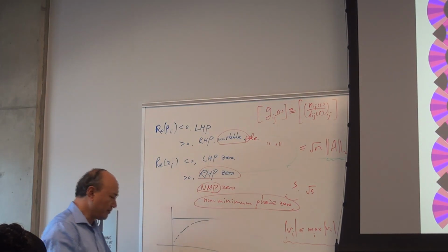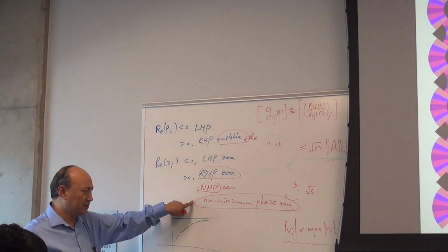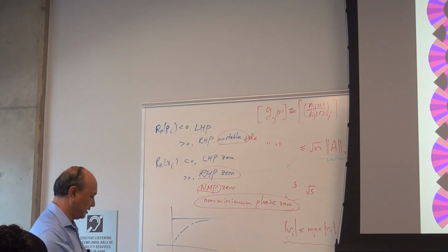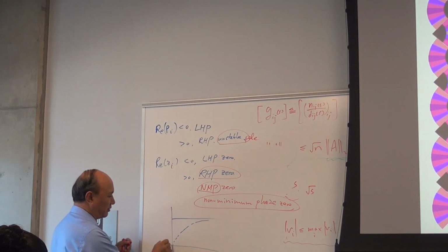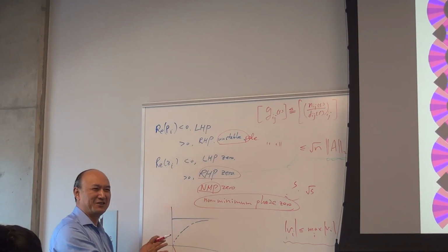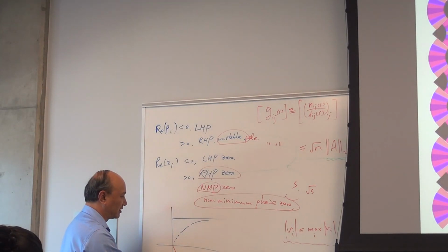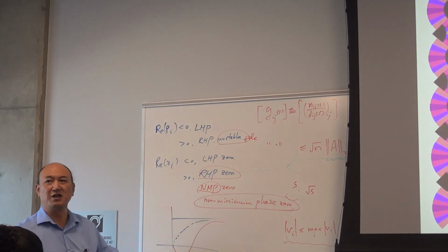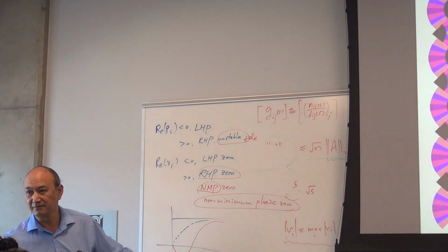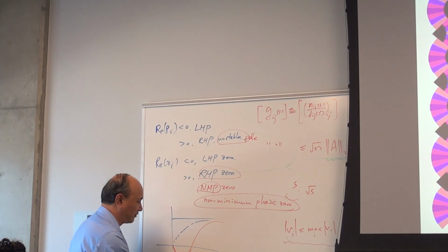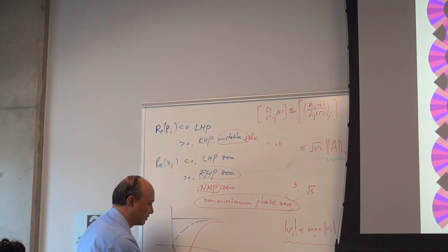But if you have a non-minimum phase zero, the zero is on the right half plane. You say follow me, and it goes directly the other way. It doesn't follow you first. The direction is wrong. Then after that, it starts to come back. This is called non-minimum phase behavior.